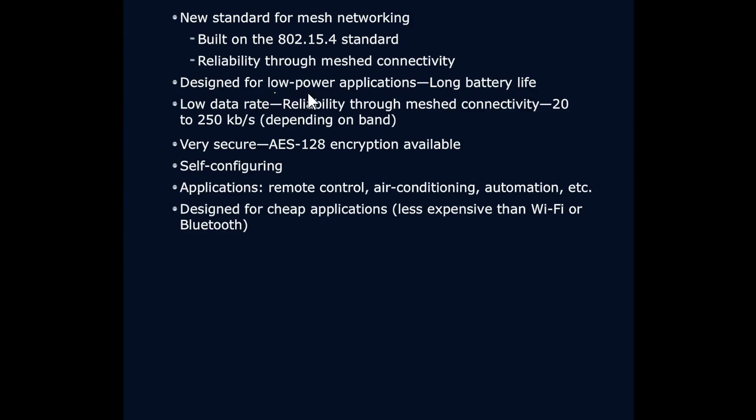All right, so it's designed to run at low power. And that's important because a lot of our end devices, I want them to be truly completely autonomous, where I don't even have to plug them in. They're running off of battery power and they can run that way for months or years without my having to touch it. But they're running at a low data rate. They'll save up their data and send it out in a burst, typically. So not a lot of constant communication. And notice 20 to 250 kilobits per second. That's not a typo, that's kilobits. Now remember, Bluetooth could go up to 24 megabits per second, and this is not that. This is much slower. So again, designed low power for a specific utilization.